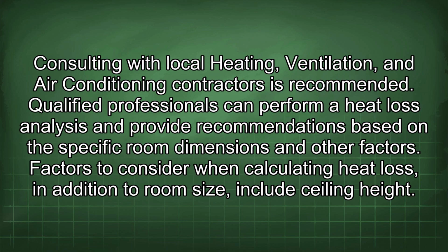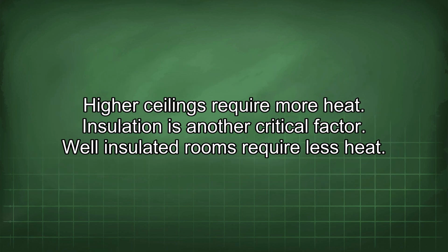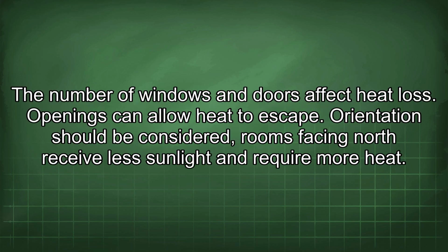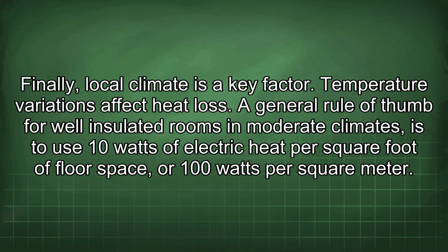Factors to consider when calculating heat loss, in addition to room size, include ceiling height. Higher ceilings require more heat. Insulation is another critical factor. Well-insulated rooms require less heat. The number of windows and doors affects heat loss. Openings can allow heat to escape. Orientation should be considered. Rooms facing north receive less sunlight and require more heat. Finally, local climate is a key factor. Temperature variations affect heat loss.